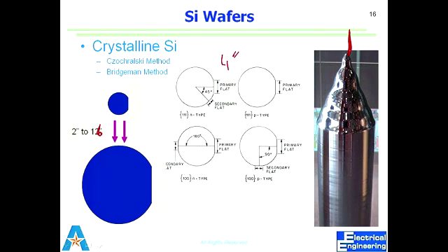Once you are given a wafer, there's no information on it. It's just a shiny disk, nothing written on that. You should know how to tell what kind of doping is in that wafer, and what's the orientation of that wafer, from the flats. It will always have a flat. More often, we hold that wafer from that flat region using tweezers.